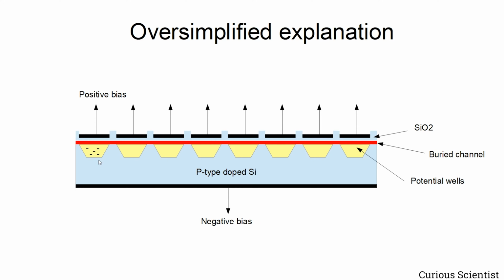And after the exposure is finished, we shift out the charge packages or packets, and then these charge packets are converted into some digital signal by an AD converter. And how it is done is that these charge packets can be moved with this positive bias.